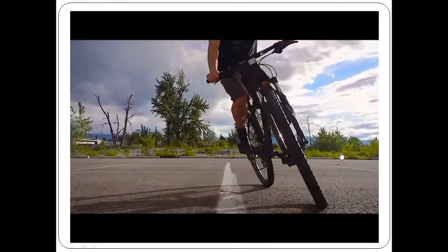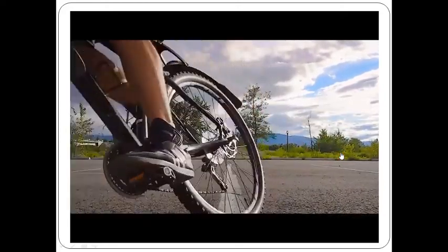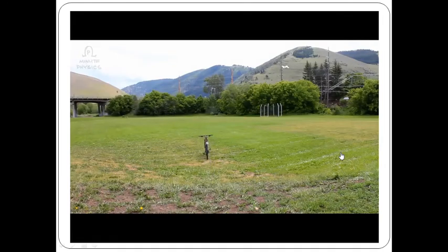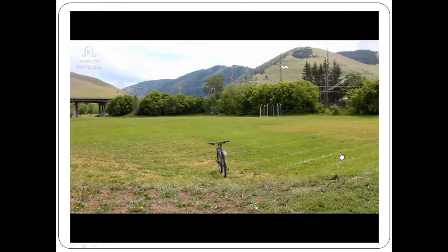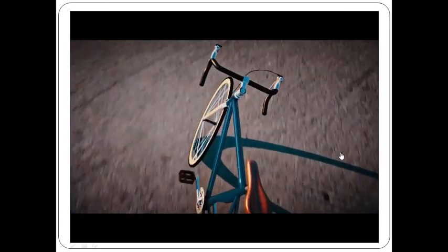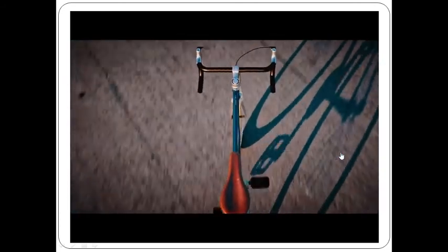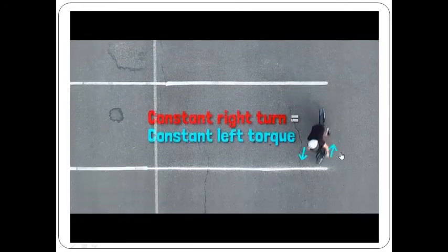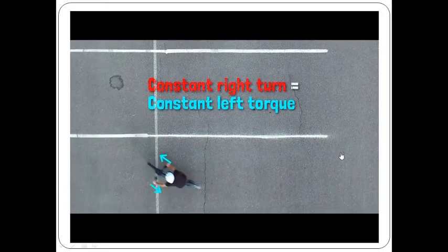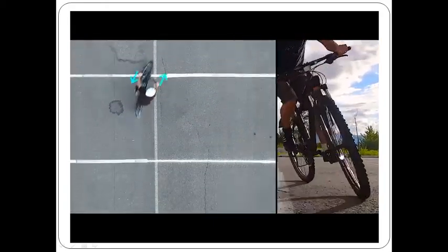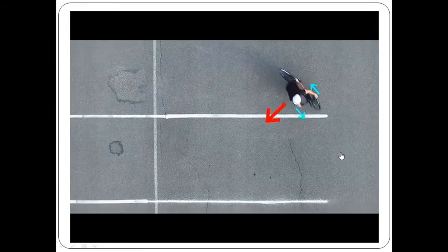Once you finally get yourself into a right turn, you'll also need to work to keep yourself in the turn, since most bikes and motorcycles have a tendency to automatically stabilize and straighten out on their own. This happens because a right-leaning bike automatically steers itself even farther to the right to get the wheels back underneath its center of mass, so you'll actually need to apply a slight torque to the left to keep the wheels from turning too far to the right. Yes, it's counterintuitive. To turn right on a bike, you turn left, then keep trying to turn left while leaning and turning right. Bikes are weird.